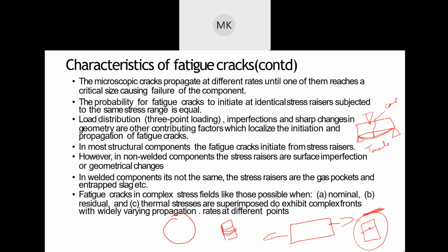The only thing that you can do nowadays is make sure that the size of the void is not huge enough that a crack would initiate from that point. But other than that, in terms of composites, the percentage of failures starting from the inside of the material increases from 10% to about 30 to 40%. But still, major cracks would start from the surface.